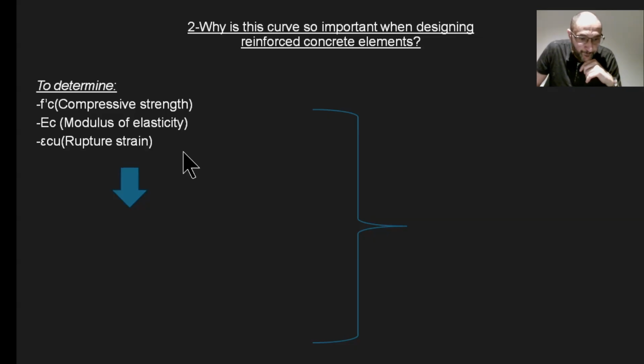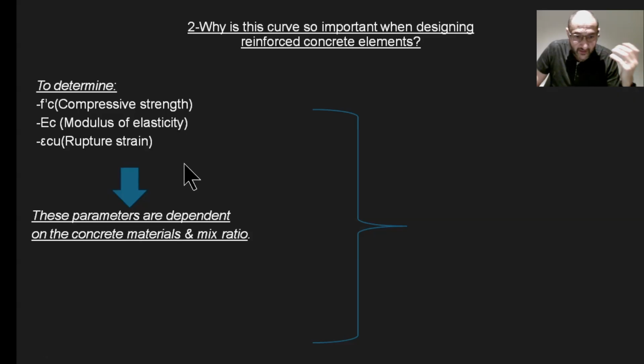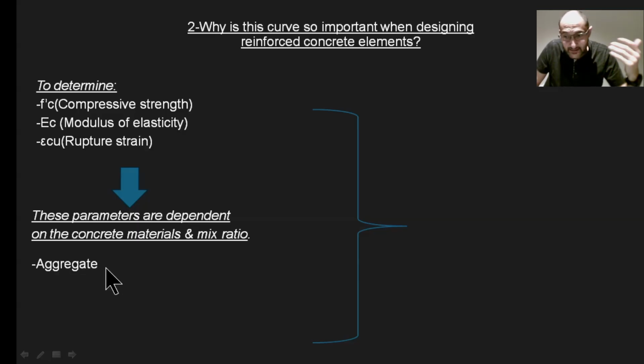All right, now what is concrete made out of? What are the ingredients? Aggregate, which is a mix of rock and gravel. We can have coarse and fine aggregates, but keep in mind that aggregates can sometimes carry moisture, and these moisture levels can exceed the saturated surface dry condition. So we have to calculate the water content in that mix, especially from the fine crushed rocks. It also has sand, and it has water and cement.